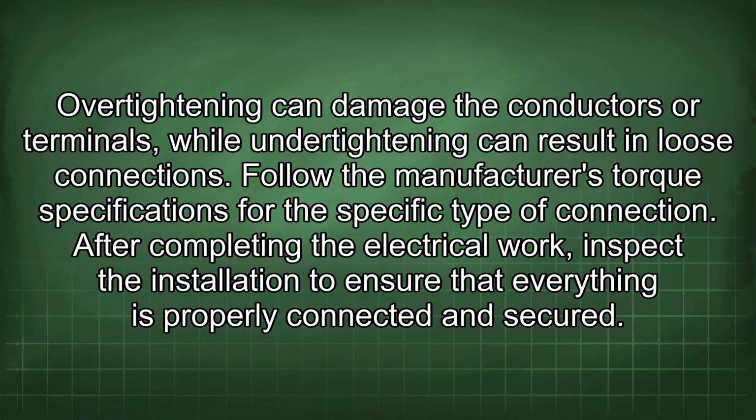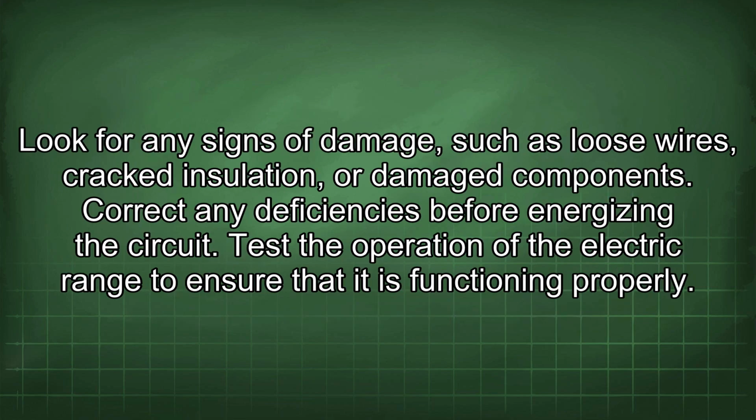After completing the electrical work, inspect the installation to ensure that everything is properly connected and secured. Look for any signs of damage such as loose wires, cracked insulation, or damaged components. Correct any deficiencies before energizing the circuit.